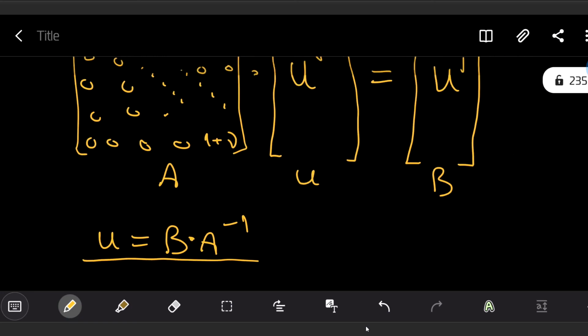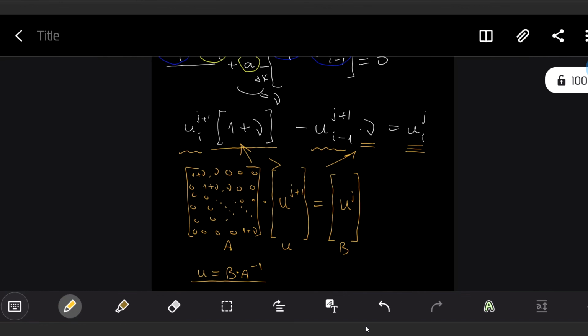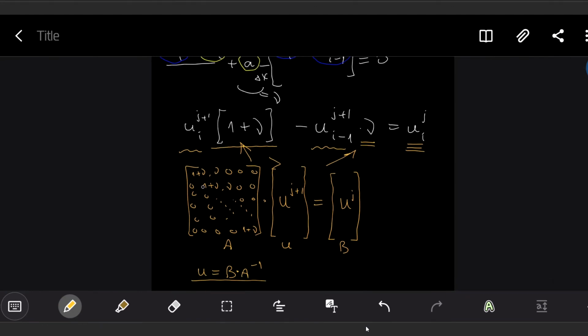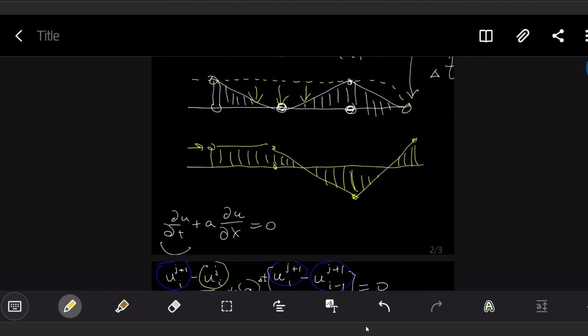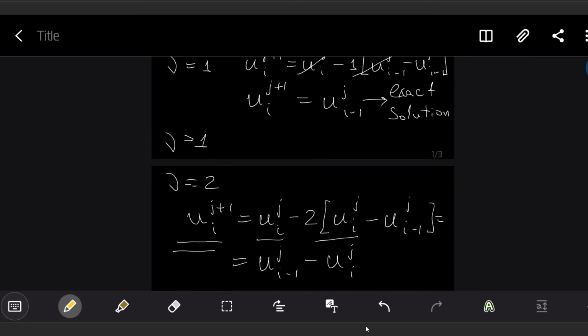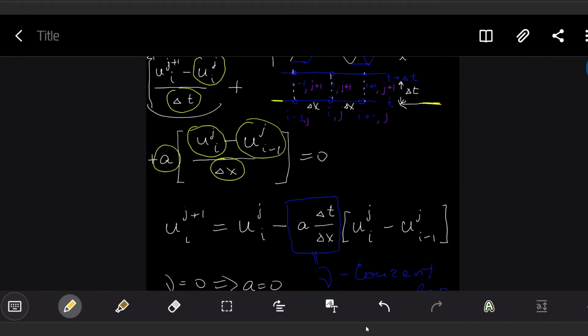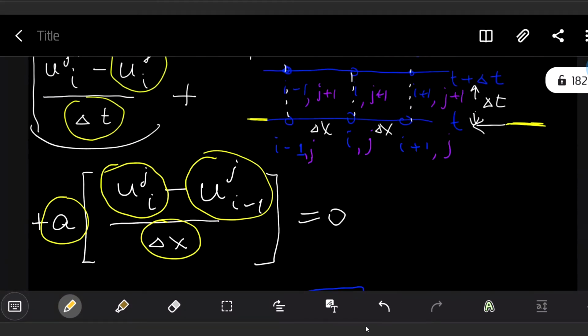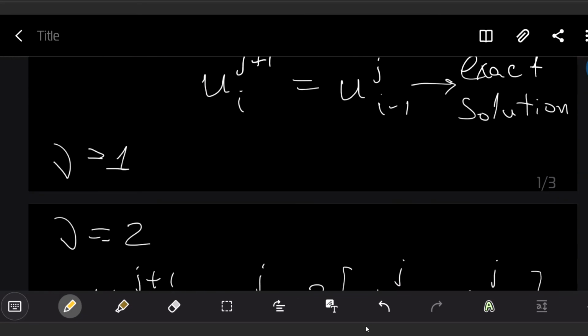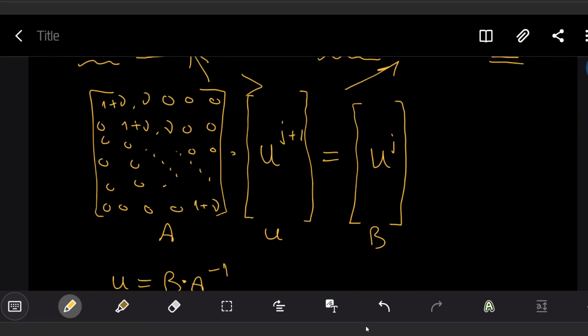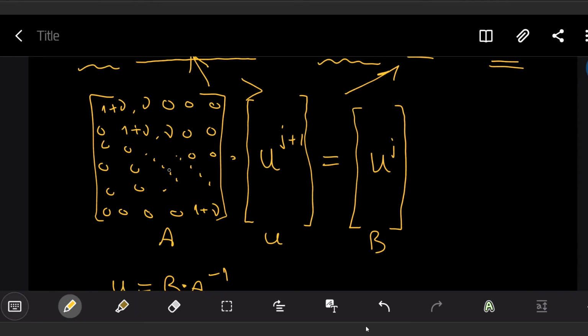This is how Fluent is working. It's just finding the coefficients of this matrix, inverting the matrix, and multiplying with a known vector of parameters. Of course, for 4 or 5 flow equations it is more complicated, more complex, but the idea is absolutely the same. And the Courant number is always entering inside these main diagonal and additional diagonals.